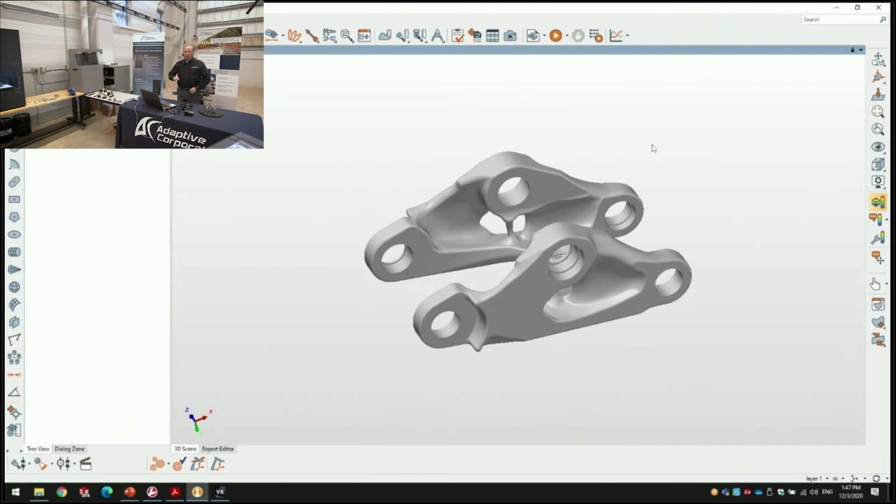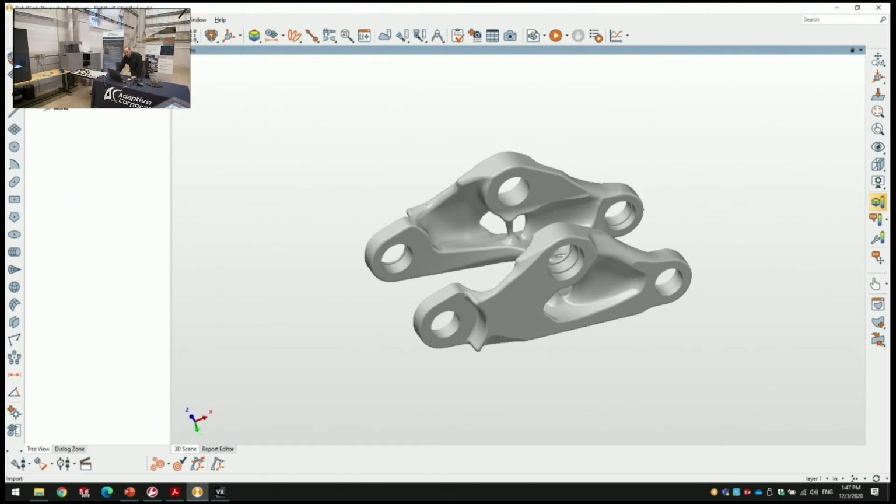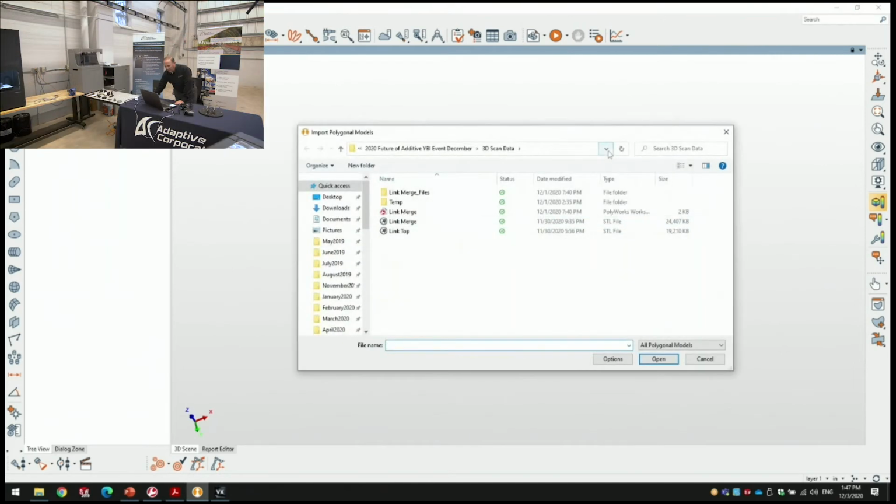And inside of Polyworks, I can open IGES, I can open STEP. If I'd prefer to work with CAD native data, they do have converters that you can acquire that would open SolidWorks native or CATIA native, or I think NX native as well. So there are a variety of direct converters. So step 1 is open CAD. Step 2 is to open up the 3D scan data.